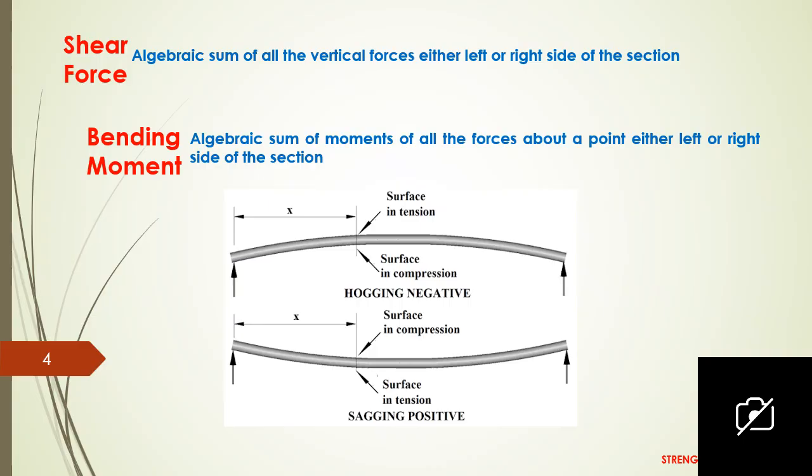To draw them, we must know the shear force values at different points in the beam and bending moment values in the beam. So what is shear force? It is the algebraic sum of all the vertical forces either left or right side of the section.